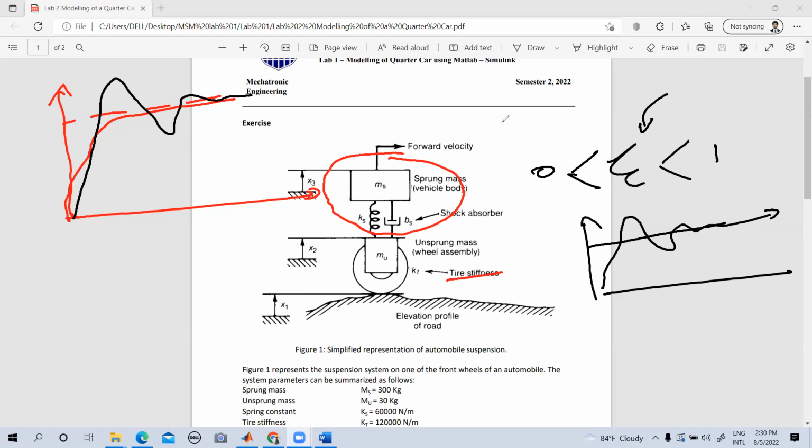So simply what we call a critically damped system is when this is equal to 1. When this is equal to 1, in a second order system, it corresponds to the coefficient of the first order term divided by 2 times the square root of the highest order coefficient into the lowest order coefficient. You can go through those notes.